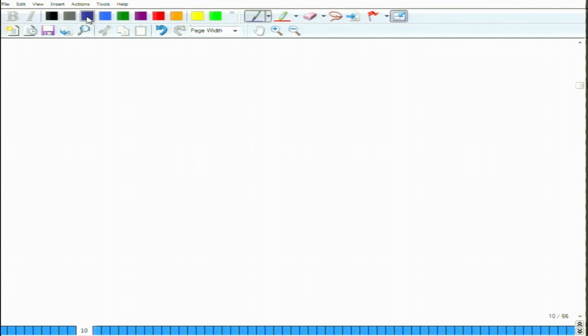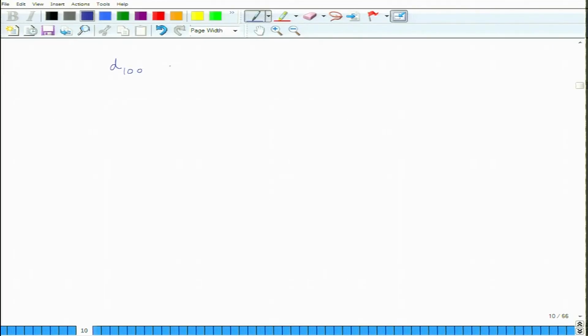Here we have finished the plane part. What we have learned is how to draw a plane, how to determine the Miller indices of a plane which is drawn, how to find the interplanar spacing, and how to find the interplanar angles. So, interplanar spacings D100, D010, D001 are all the same for cubic.